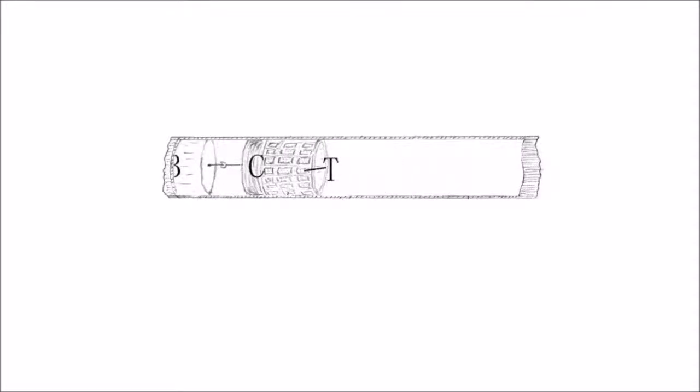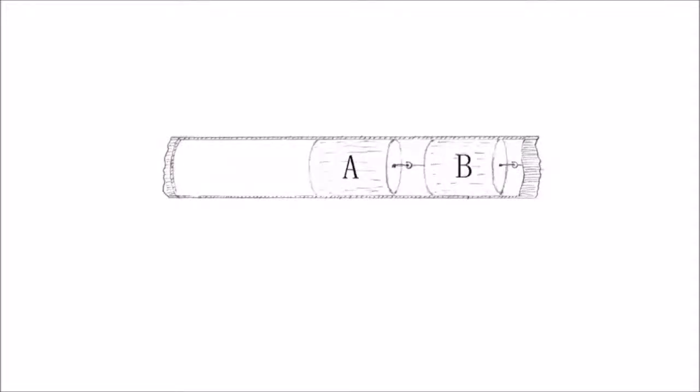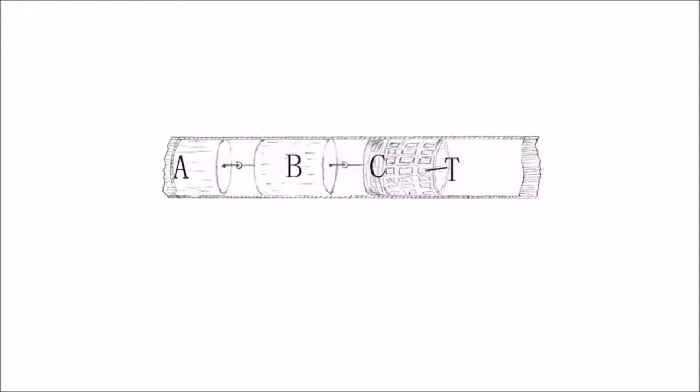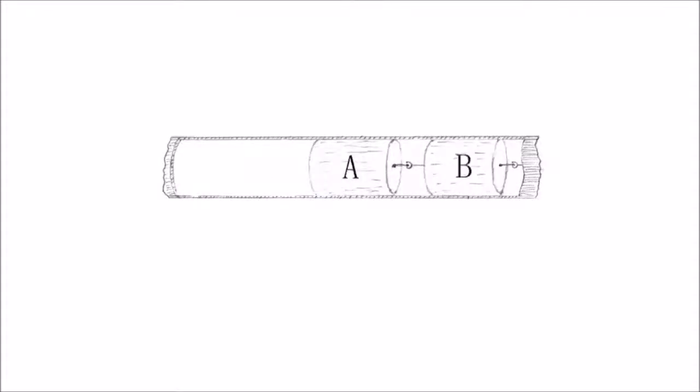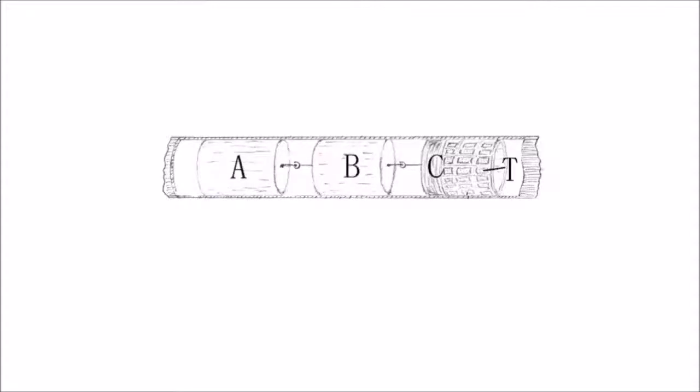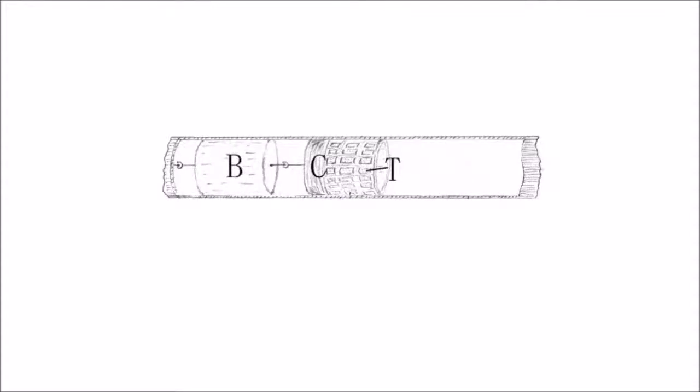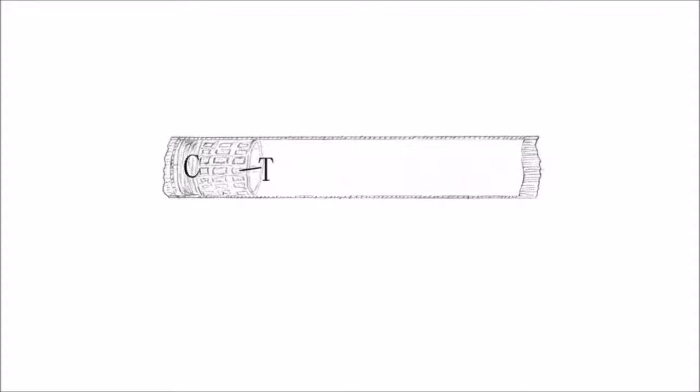This equipment is transported inside the pipeline by the flowing crude oil, while at the same time ultrasound measurements are performed. This method can be used to assess up to hundreds of kilometers of pipeline in one run. This figure is a schematic view illustrating such a device.